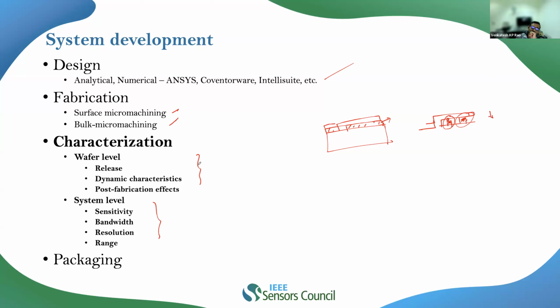That is basically a problem of stiction, and it happens since there is no release of the oxide layer. We need to see, as the first and fundamental thing, whether my structures are released or not, right? That's the first and fundamental thing. If we go forward for the packaging and the structures are not released, then the industry is in an utter loss, right?